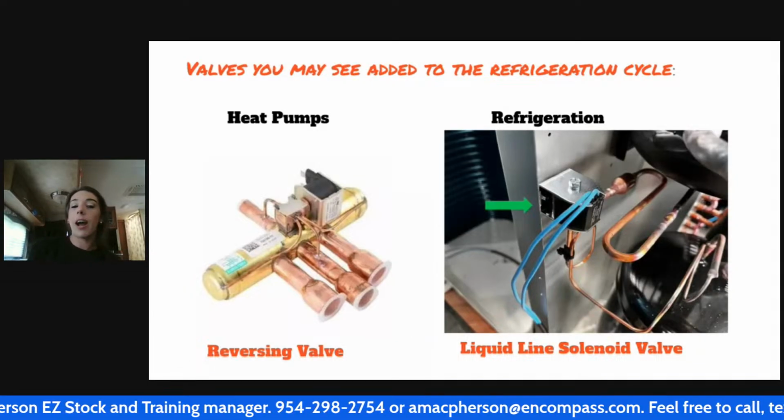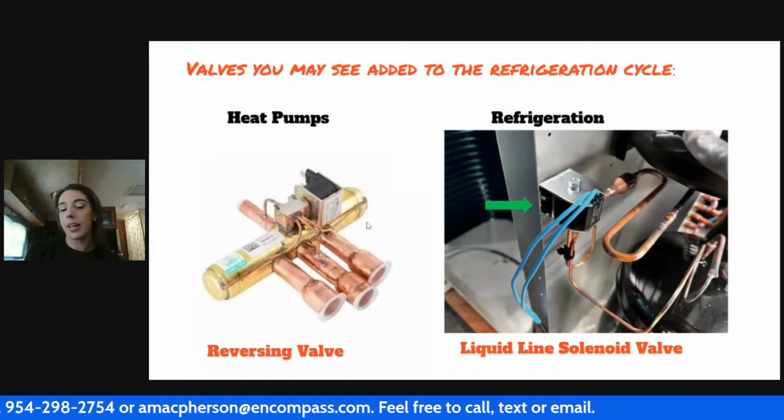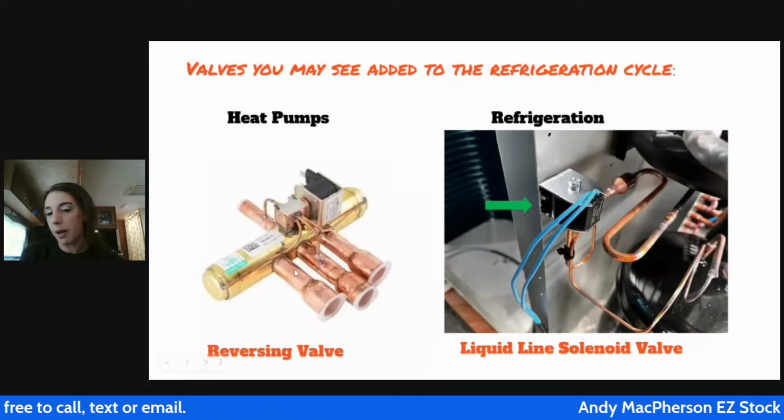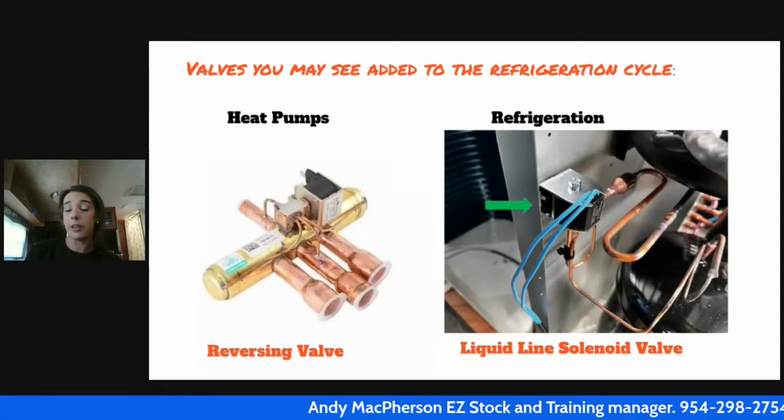It's going to go directly to the reversing valve. And this solenoid is electrically powered, and it's going to talk to the thermostat. It's going to talk to the unit. It's going to talk to the outdoor ambient temperature. It's going to be either energized or de-energized on cooling or heating, depending on the brand.